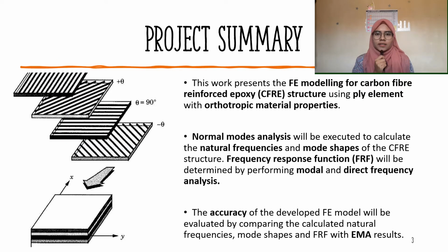First of all, let's start with the project summary. This work presents the FE modeling for carbon fiber reinforced epoxy structure (CFRE) using ply element and orthotropic material properties. To determine the modal parameters, which are natural frequencies, mode shapes, and frequency response function (FRF), normal mode analysis and modal and direct frequency analysis will be performed to calculate those parameters.